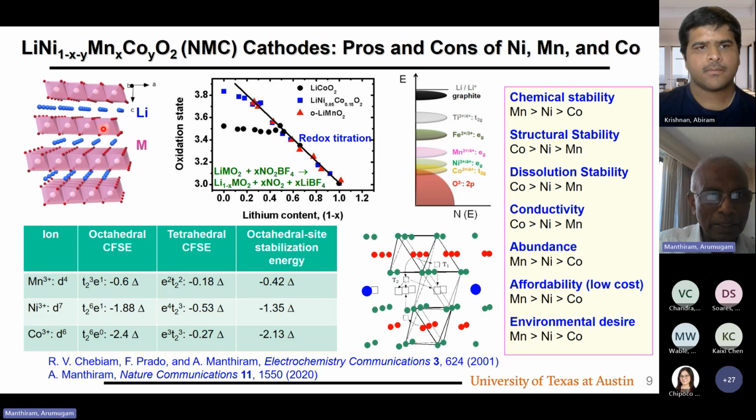Here it is in the octahedral site. It may tend to move to this six-fold octahedral site, but when it moves, it cannot directly jump. It has to go through an intermediate tetrahedral site, as you see here. So that means if this ion does not like tetrahedral site, then it won't move.